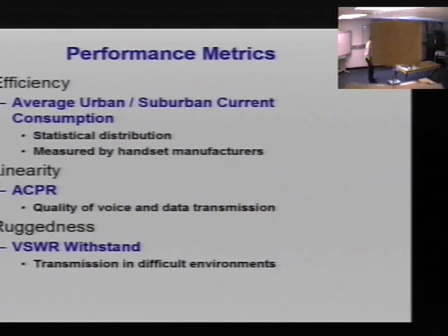And the other thing is, silicon inherently has some issues with VSWR, which is the antenna mismatch. You have to handle a mismatch and still meet linearity, and currently there are requirements where you cannot use an isolator. An isolator is a ferrite component that provides you with a 50 ohm input impedance regardless of what the output impedance is. So the antenna can see all sorts of different environments.